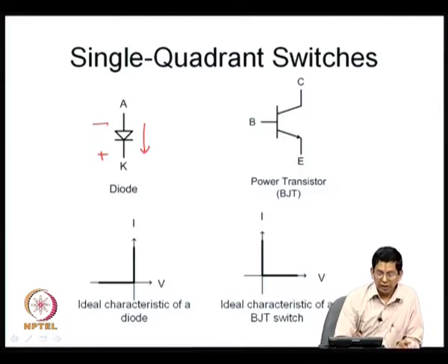So, I have indicated the IV characteristic, the current to voltage characteristic of a diode acting as a switch. This is nothing but the idealized characteristic of the diode that you are aware of. In the actual characteristic, you will have a small exponential current going on here, that is a very small value, and if you ignore the forward voltage drop, you get such an idealized characteristic.